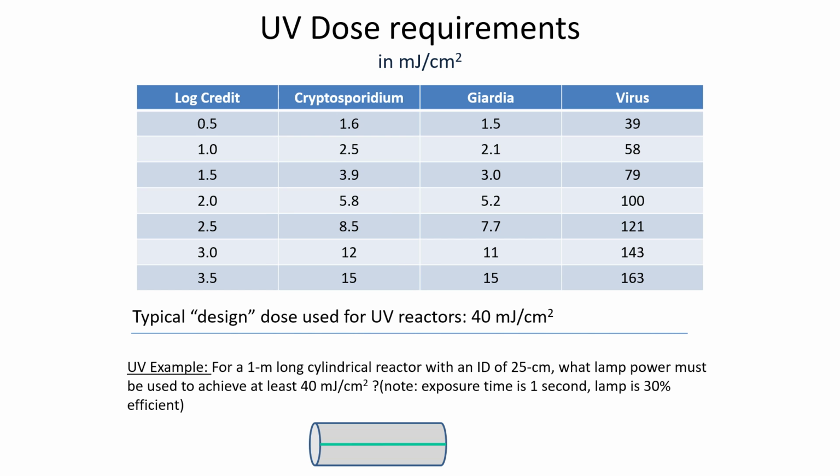So the area that we want to be thinking about is the circumference, the outside area of that, multiplied by the length into the page. The 1 meter long cylindrical shape of that gives us the area. So the area that would apply here would be pi d for the circumference, pi times d, and then multiply that by L to get the overall area.